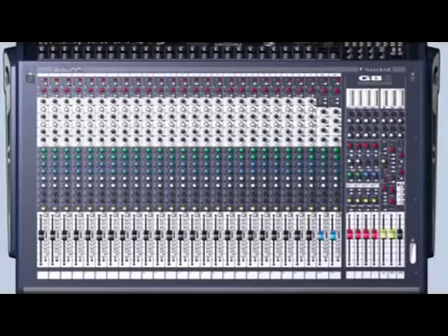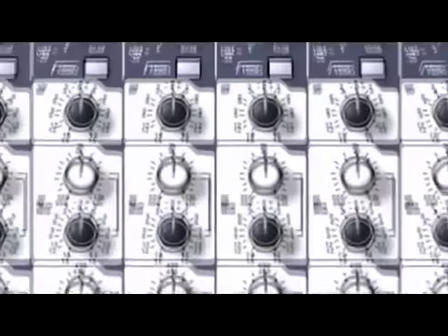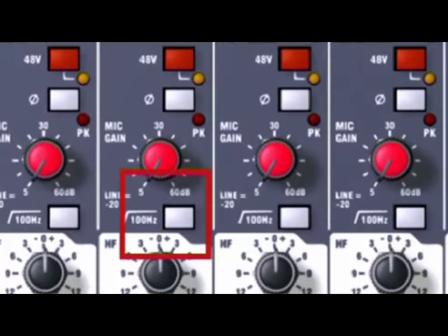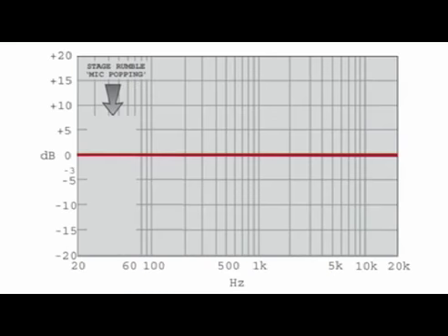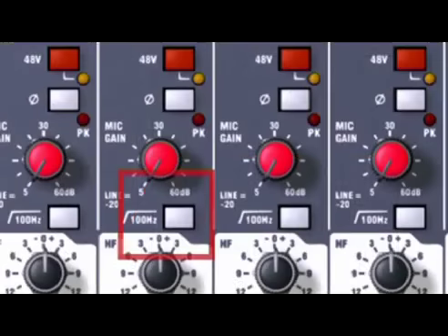The high-pass filter cuts out very low frequencies, but lets all the others through without affecting them. You can use it to clean up boomy instruments, or to take out rumble from people jumping around on stage, air conditioning, or even tube trains. You probably wouldn't use a high-pass filter on a bass guitar or a bass drum. Used appropriately, a high-pass filter can make your mixes sound cleaner and less muddy.